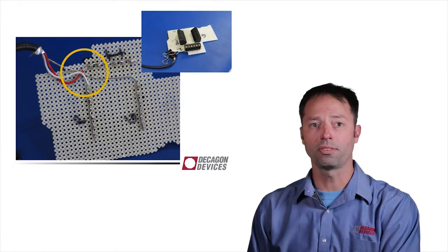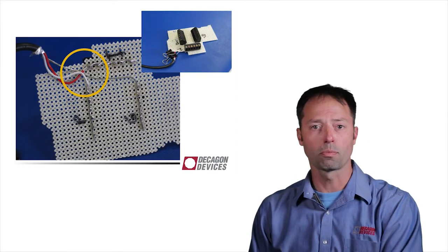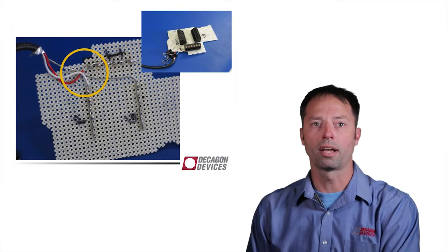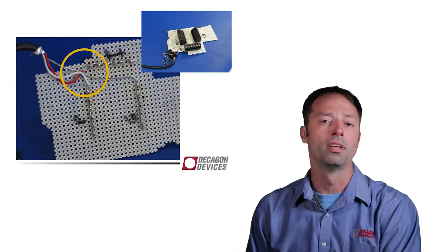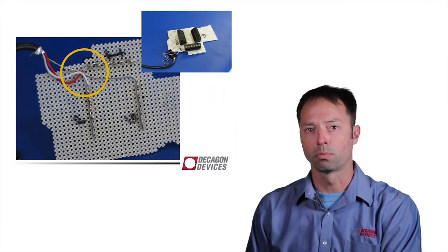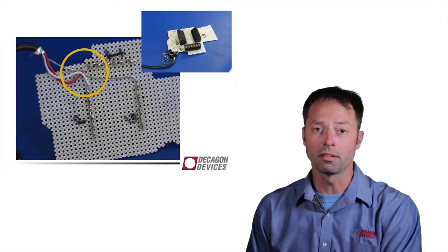One thing to point out with this, this is great for a bus that I use around Decagon for testing sensors. But note here where I've got that bare line just barely not crossing the red line. This is an example of a case that could cause a real problem. If you short those out, you won't get any data for any of the sensors on there.